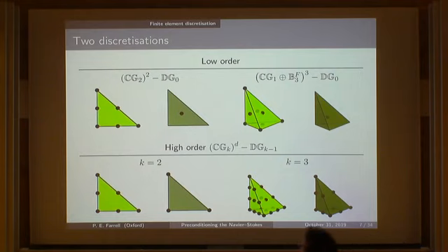If you're not familiar with this finite element notation, let me just briefly explain. This is the element I use for the velocity. This is the element I use for the pressure. So this is a continuous piecewise polynomial representation for the velocity that's quadratic on every cell, and this is a discontinuous representation of the pressure that's piecewise constant. Then it turns out that the natural 3D generalization of this is very expensive. So this element is inf-sup stable in 2D, but not in 3D. So if you want a stable discretization, you would probably go to CG3 DG0.